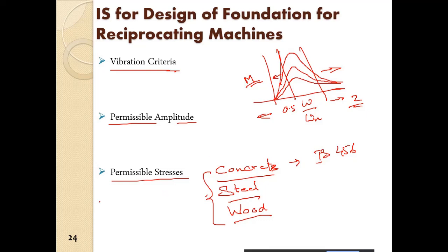Apart from that, definitely the permissible stresses in the foundation soil. In the foundation soil, that has to be within limit. So that is one important criterion. We can look into IS 1904 for looking into that aspect.